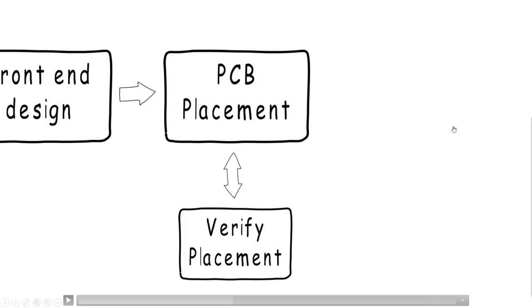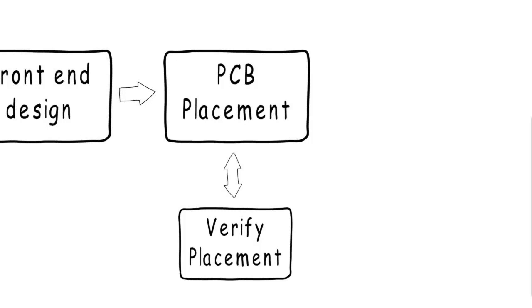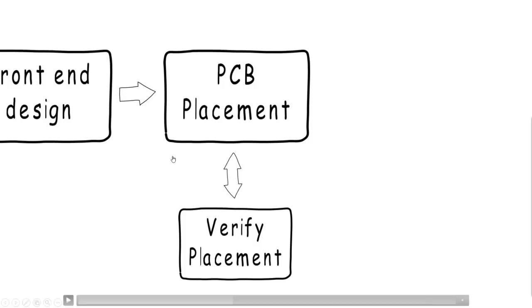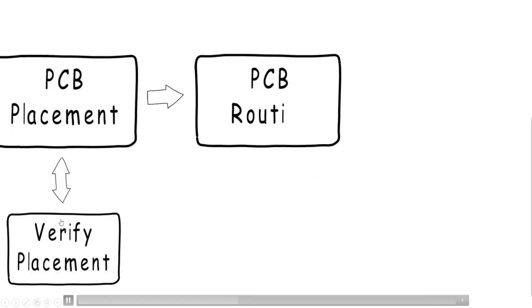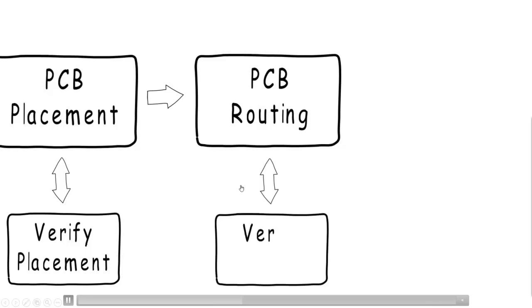So if something is found later on, even with a physical review where you have people in a meeting physically looking at the board graphically, and they find a problem related to manufacturing, you then have to fix a lot of the critical placement items that you've done, which affects routing, and therefore, again, slows down the design process. But if you continue through your design process using the Valor NPI tool or some other manufacturing validation tool, you'll fix those problems before they ever occur.